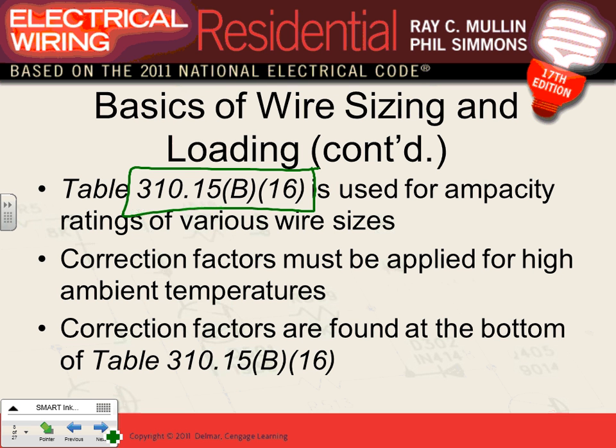And then the last factor, so that will make them 5, is are you grouping these conductors together in one conduit, or are you sending them in cables separate, no more than 3 current-carrying conductors? So we will get into this next chapter, and I'm going to leave hashing out this table until next chapter on Monday. We're going to go to 3.16 and I want to walk you guys right through the table, how to use the table from now until you graduate from here.